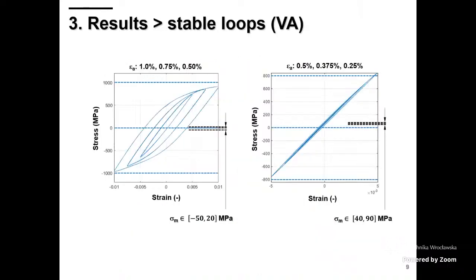So I would like to show you two examples under variable amplitude loading regarding the midlife cycles. Here we can see an interesting effect. In fact, we have found a mean stress effect. If we compare the maximum and minimum values, we can see that they are not similar. The cycles are not symmetrical. So we would like to include these values in our fatigue life prediction model.